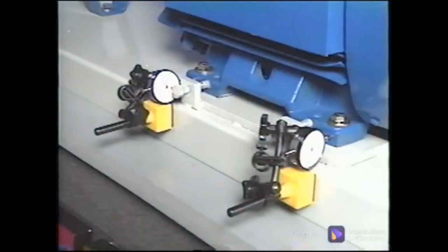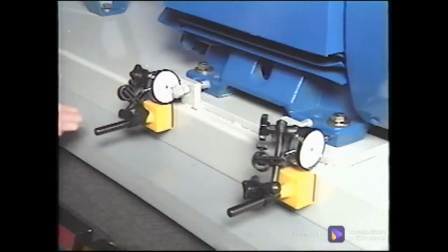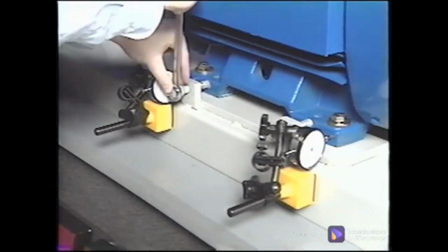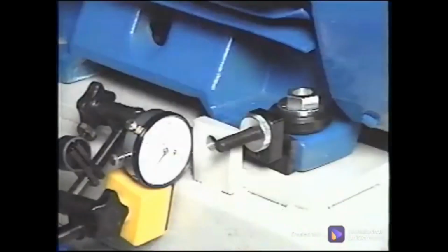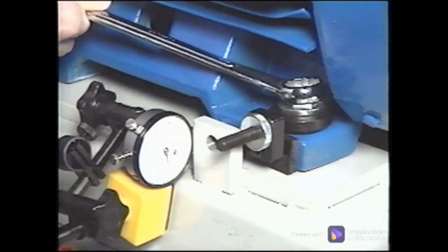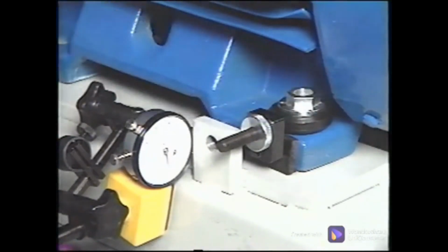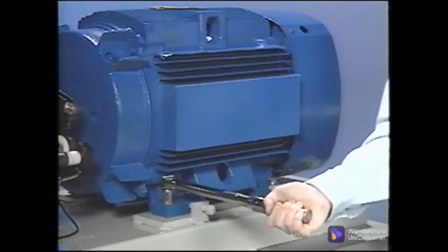Repeat the steps, solving for the vertical move of the outboard feet and the horizontal moves at each set of feet. When moving the machine in a horizontal position, set up dial indicators at each foot that will be moved, being sure to set them to 0. As you push the machine with the jack bolts, watch the dial indicators and move the machine the calculated distance. If no jack screws are available, temporary jack bolts may be mounted on the nuts of hold-down bolts to move the machine horizontally. When the machine has moved the calculated amount, torque the hold-down bolts and take another set of readings. Repeat the steps until the machine is within tolerances.